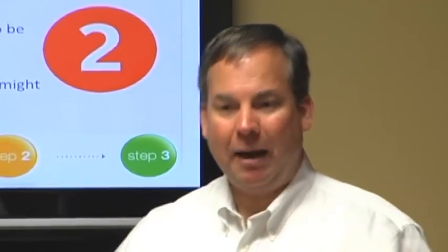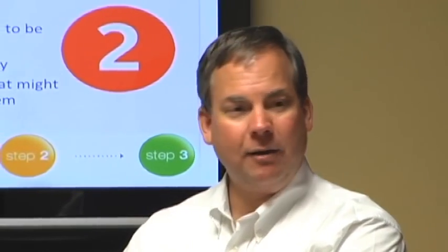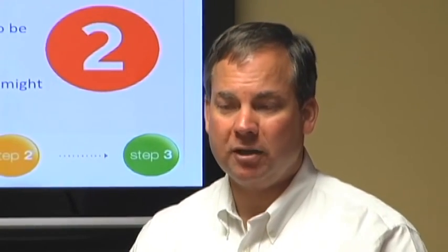Okay. If you're MatCor, we're located here near Philadelphia. The Delaware River changes seasonally. In the summer, the salt line moves up the river, and you end up with very low resistance, very salty, corrosive water. In the winter, that salt line tends to move back towards the ocean, and you'll have more fresh water, less corrosive, but also more difficult to flow current through because the resistance of the water's changed a bit.